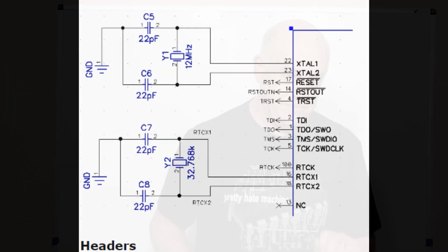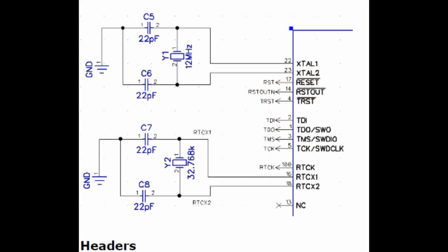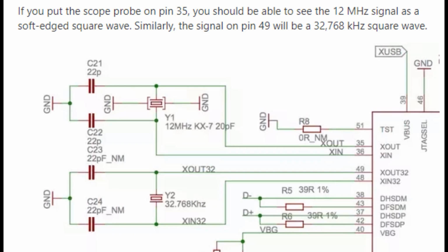So when I decided on this topic, I said to myself, maybe things are different since the last 4 years I was at Microchip, where I was seeing this issue all over the place. Let me just Google and see if maybe there's some stuff out there on the web that's not incorrect. So here's the very first thing I Googled when I typed in crystal oscillator MCU. Notice all 4 capacitors are 22 puff, which is great for the BOM, but it's not great for that 12 megahertz crystal. And actually 22 puff may be correct for the watch crystal.